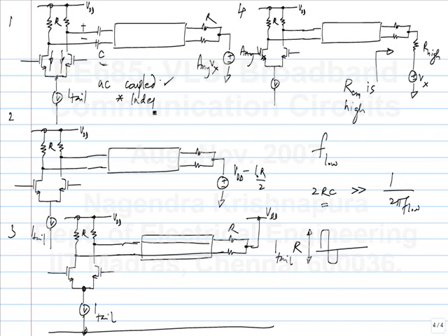When we are comparing transmitters, we should be comparing transmitters that provide equal swing. So at least now we know that all transmitters provide the same signal swing. The comparison will be on some other basis. For the first one, we already identified some points: the DC bias is independent of the receiver, but you may need large C values. What about the rest? What's the difference between 2, 3, 4, or is there no difference at all?